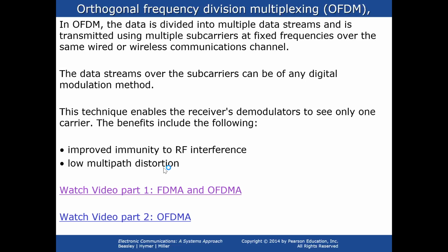As we know, a rectangular function can be represented in frequency domain as a sinc function which is centered around DC. When multiplying the signal by a carrier frequency in time domain, the signal will be shifted in frequency domain by the same amount of carrier frequency. Thus, we can represent these modulated subcarriers in frequency domain as a series of sinc waves centered around the carrier frequencies. Basically, we are having 1,200 such sinc waves.